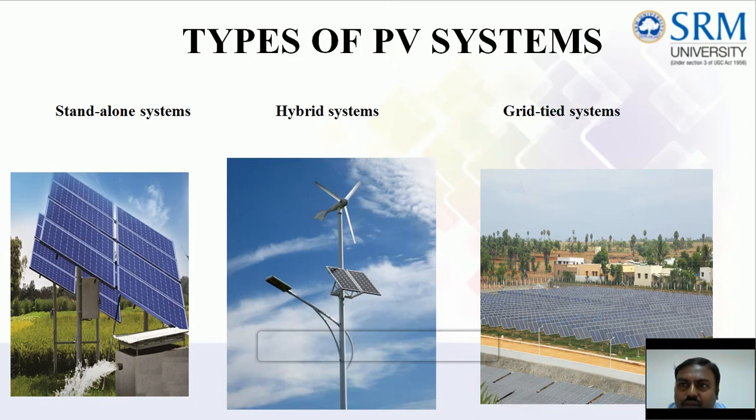Approximately, on a gloomy day the wind will be more, and on a sunny day the wind will be less. So these two sources complement each other in nature. Therefore, this is a good blend for hybrid systems. Not necessarily must the wind electric conversion system always be connected with a photovoltaic system. It can also be interacted with other sources like fuel, diesel generators, and so on.